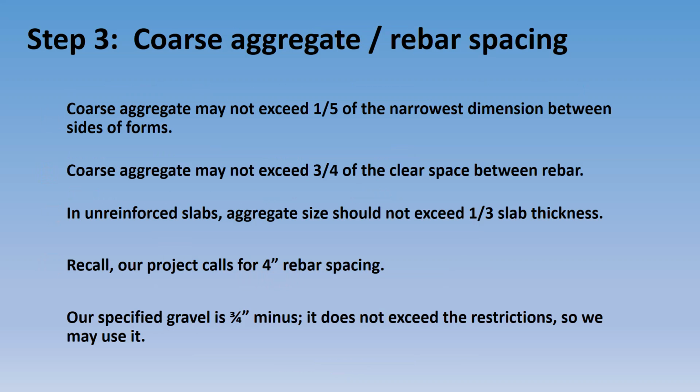You would only find that on something between an interstate and an airport runway. Our specified gravel of 3/4 inch minus doesn't exceed that restriction, so we're allowed to stick with it and use it.